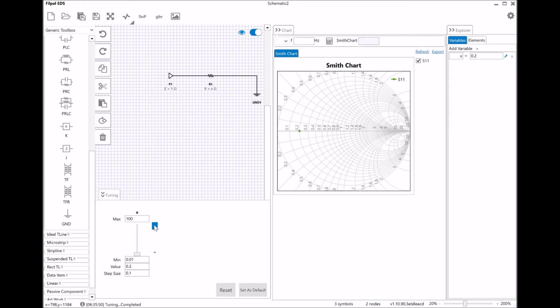So you see, if I increase the value of the resistance or the impedance, which is the most commonly used term for the load, the impedance has the real part and imaginary part. For this one, the imaginary part is equal to 0. So if I move the impedance to higher value, you can see that the point is moving to the other side. So as it increases further and further, it will reach the end.